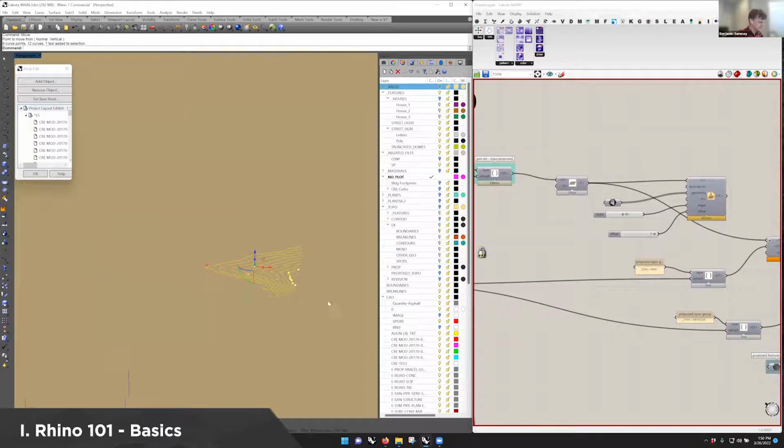But that's pretty straightforward Rhino stuff too. Rhino 7 does have an added piece to the gumball, so remember to be careful with that. Someone ran into it yesterday: the little dot in the middle of the arrow is actually an extrusion command for the gumball, so it's like an automatic extrusion. If you're elevating something, be careful not to accidentally hit that little knob there.